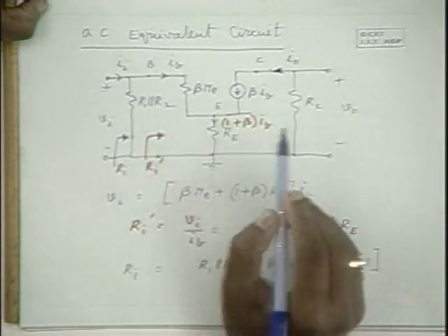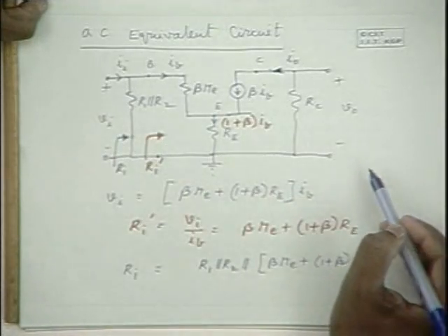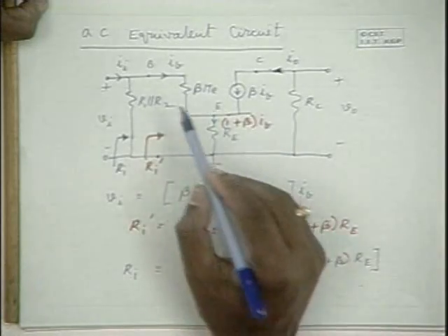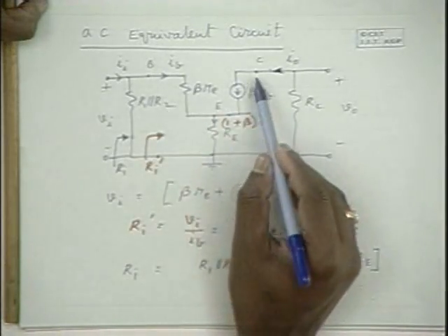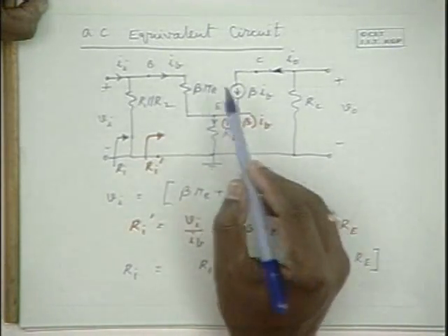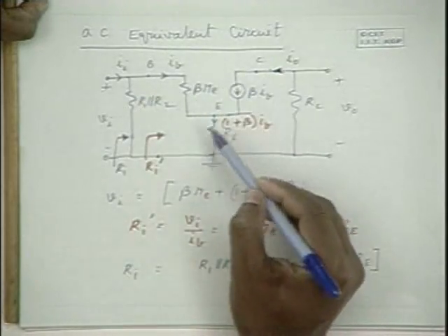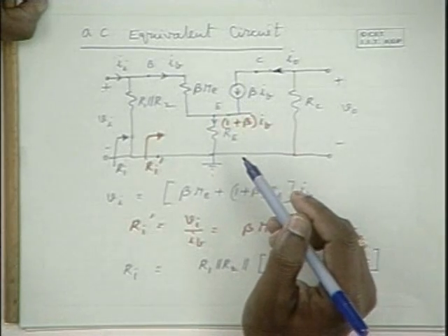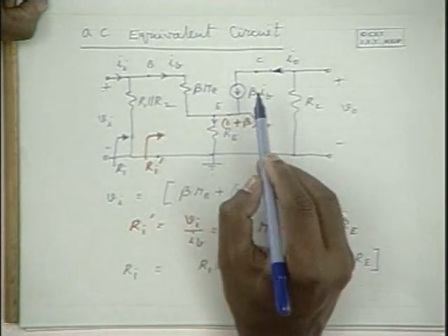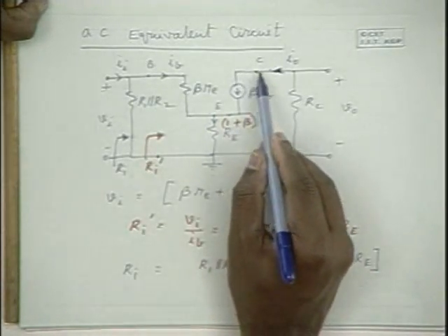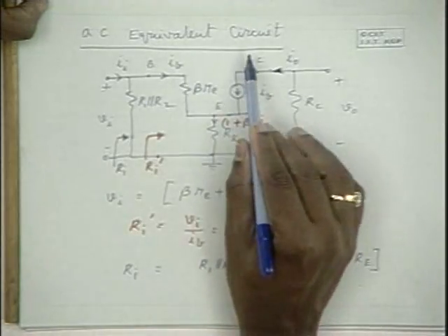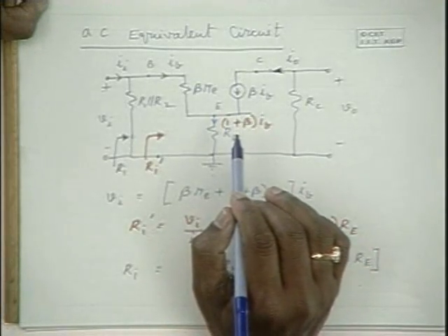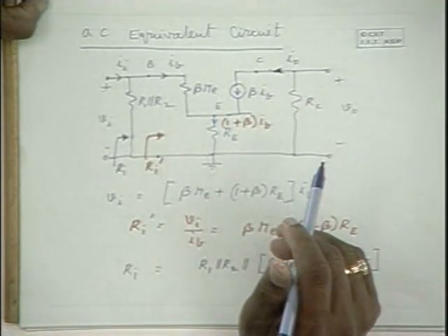Now, if you replace the input over here, please note that there is no driving voltage on this side, and when you apply some driving voltage here, IB will be 0, and this current also would be 0. Therefore, nothing flows inside, no current flows inside. That means it is an open circuit and the impedance is infinity, excluding RC.